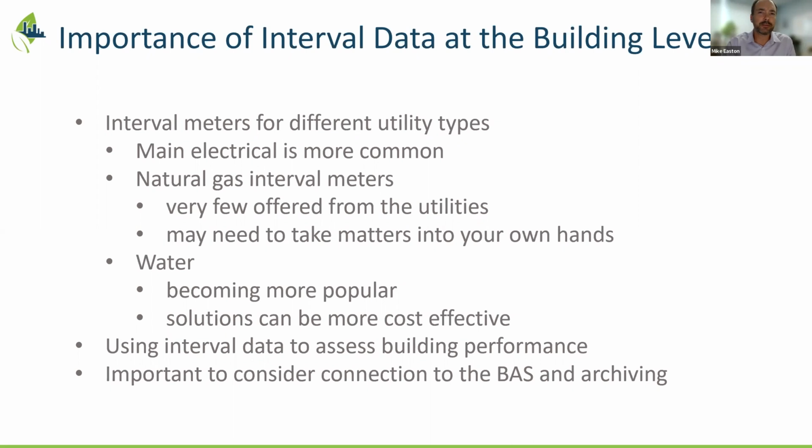Yeah, thanks, Frank. Across Canada, we'd estimate that probably about 50% of utilities, maybe 60%, offer a pulse output from their main gas meter. This is on larger buildings like institutional or industrial properties. Even if the meter itself does have an upgrade available, you still need the utility to have the policies and the expertise available to do that upgrade for you. We have had a lot of success doing this across Canada with Enbridge in Ontario, ATCO in Alberta, and Fortis in BC, which all offer not only the upgrade modules, but also the people and procedures to do the upgrades.